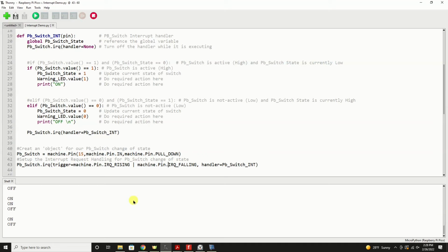And one of the most common advices to deal with this is to put a pause or a dwell or a sleep in your program. And I've found that to be very unreliable because what we're trying to deal with here is switch bounce, and that's an unknown. It's a random amount of time. And if we put a fixed amount of time up here somewhere to let that switch bounce settle, well, guess what? If the bounce takes a little longer, then it's not going to catch it up here, and then the problem kind of keeps going.